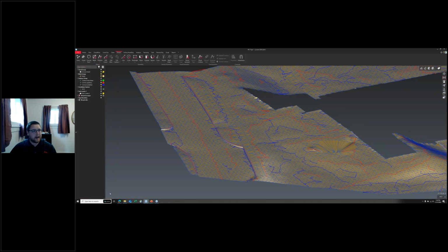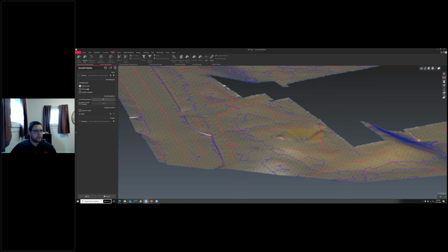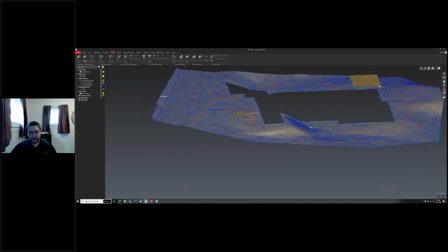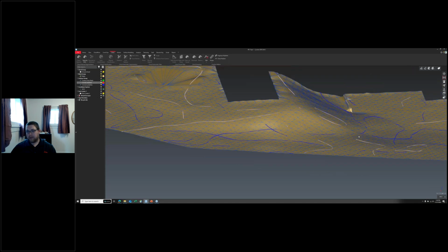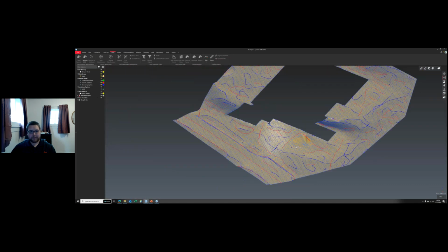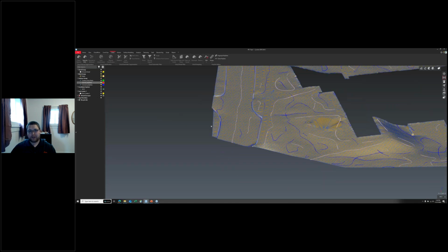And then I could select these lines, go to the clean edit, and smooth them out. I'm going to say hard smoothing intensity. Now these look a little more like what I would have for this red one as a top of bank, and over here is a top of bank. These blue ones, I could probably recycle some of them as my bottom of banks and center line of the road. It's a good way to pull some of that out and make sure you're not missing something.